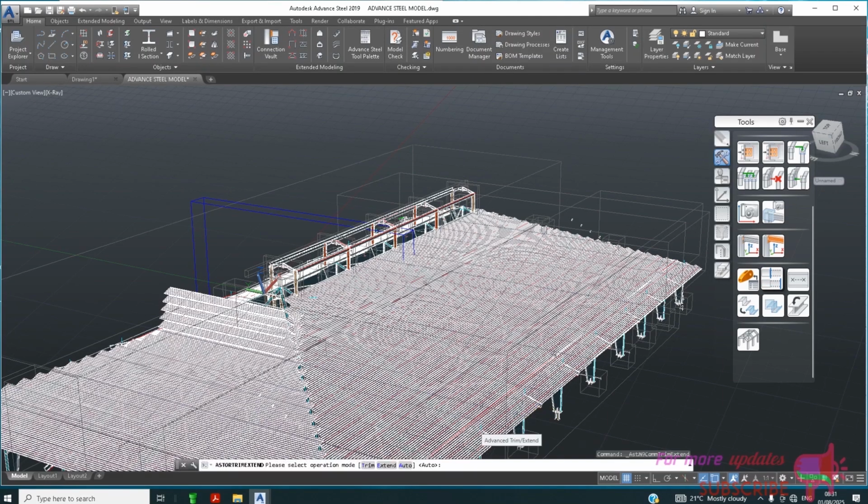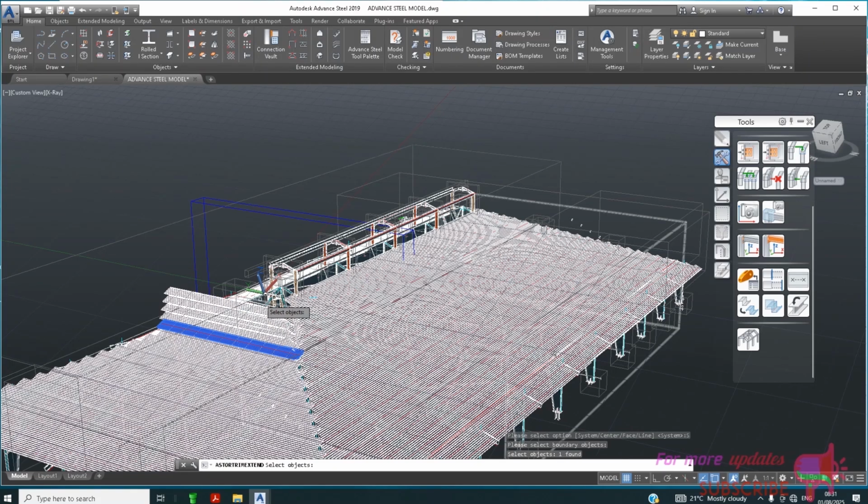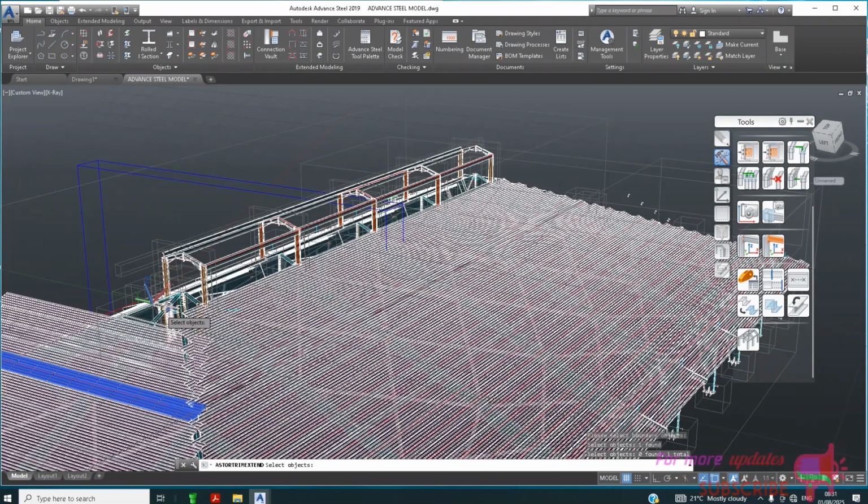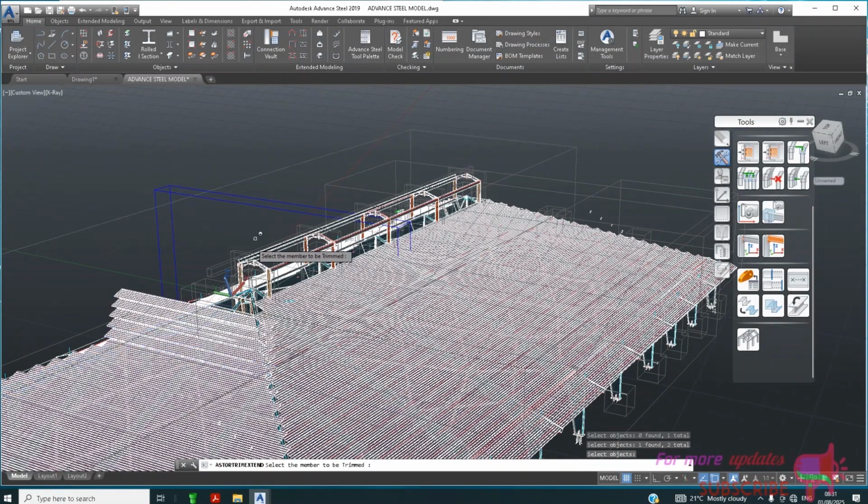So just click trim by system and add hip. You should always pick the right side that you want to be trimmed. So we have now picked our hip. Then right click. The area I want to trim is that side. Okay, and that side, the outer side. That's that side and that side. It only trims the side that you pick.